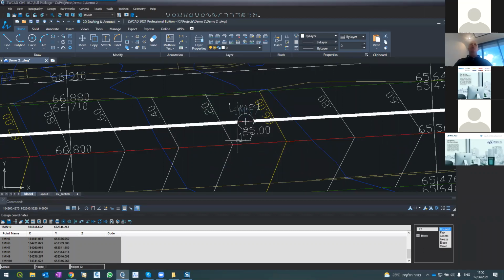This is manhole 1. This manhole is 1 because it's the serial number of the manholes. But if I scroll to the right, I can also enter the depth and the diameter of the pipeline. So let's say it's a 400 millimeter pipeline. I'm using millimeters, but I can use whichever units I want.